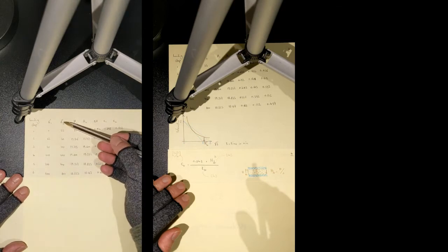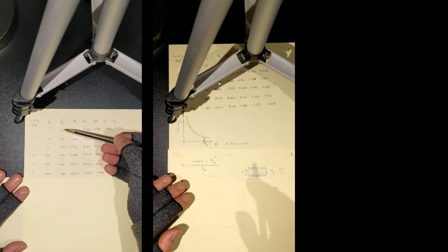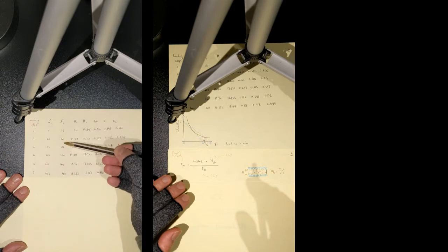That is 24 hours. So look at this. What you have here effectively is sigma dash 2, the stress which is applied to the soil specimen, and e2, the void ratio that the soil adopts at the end of 24 hours under these values of stresses. So you have a data set, effective stress versus void ratio, and this can be plotted like this.